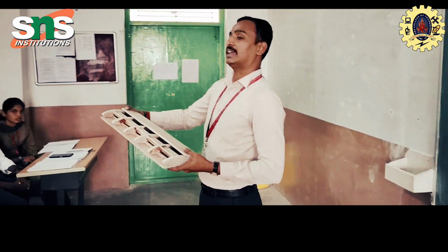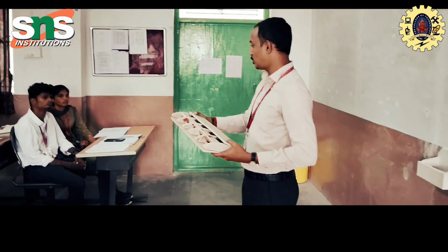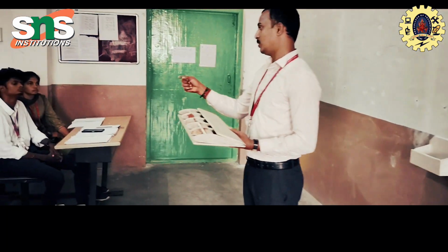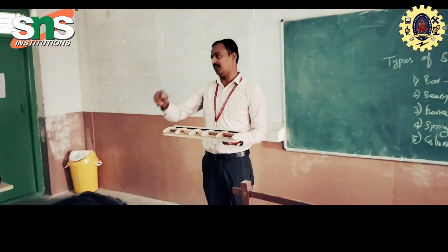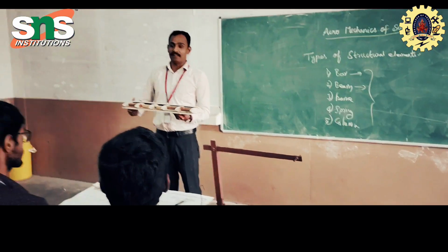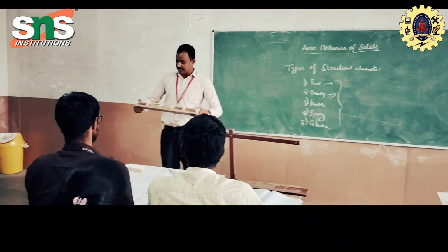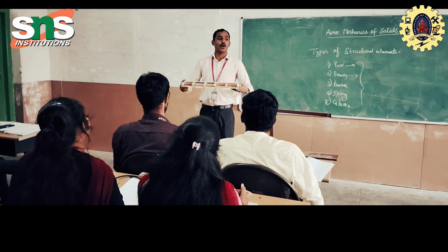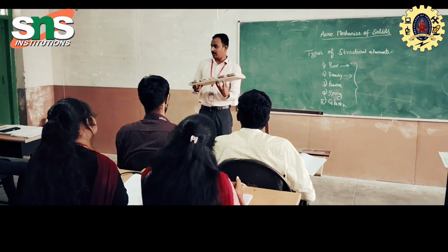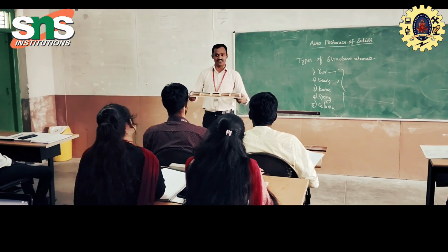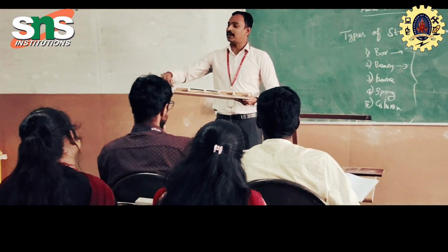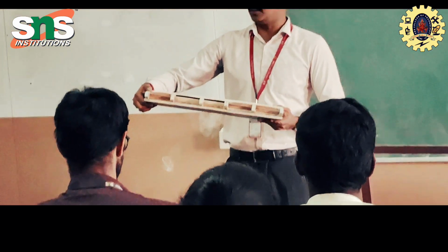Here we will take two types of load. One is structural load, another one is aerodynamic load. We know the aerodynamic loads are lift, drag, thrust and weight. Whereas the structural load has to withstand all the engine weight, the overall payload weight, right? And its own self weight. So this element has to have stiffness.